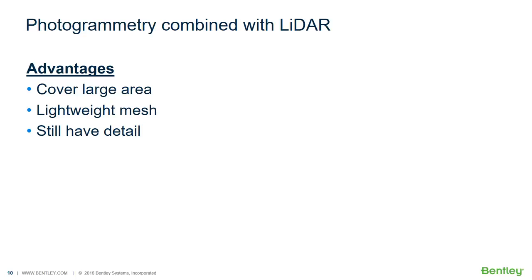Lighting's not as important if we're also using LiDAR with it. LiDAR doesn't matter if there's light or not. It's still going to calculate that angle and distance for that laser beam and give you an XYZ point. Then we could use photographs to acquire the colorization to it, which we could acquire during the day. So that's very helpful. Many times you want to do LiDAR scanning off hours, which is at night, so you don't have many people walking around and maybe the rail lines aren't running during that time.